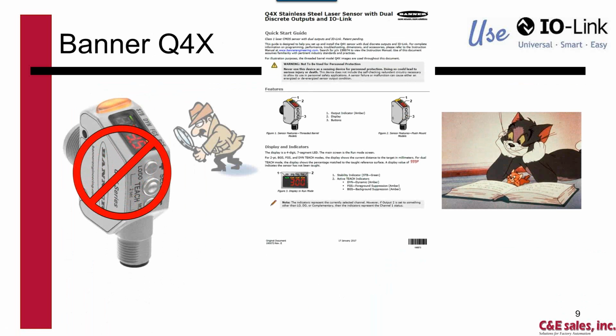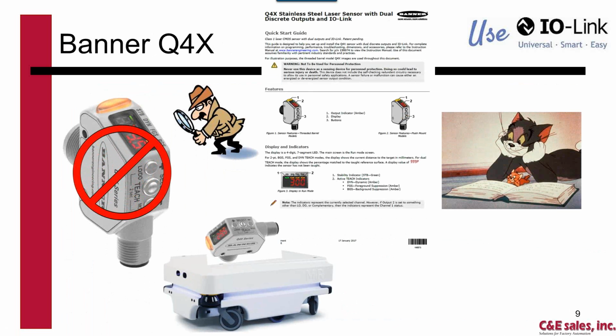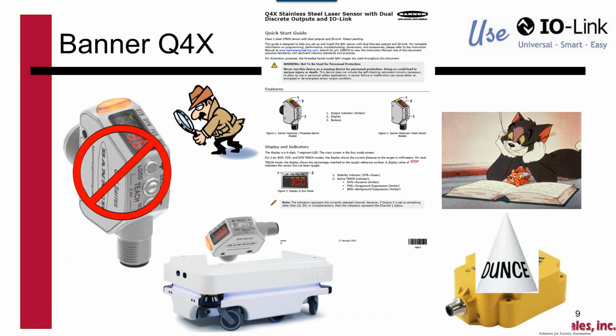Once the sensor has been identified as being failed, a replacement sensor has to be located and brought to the machine. The data sheet has to be found and the sensor has to be taught. It could take several minutes more to replace a teachable sensor as opposed to a dumb sensor. A simple sensor replacement was only possible for dumb sensors, but not for teachable sensors.